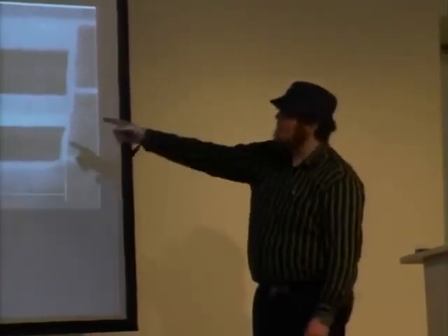This is made out of normal PCB board, and normally they say copper doesn't work because it wears off too quickly with the alumina, but this is the hardest process we can run on this machine, and it's still stuck after 400 microns of digging into the PCB board. So that works fine. So you can do this with a laser printer, with an iron, and a powder blasting machine. You can make something like this.